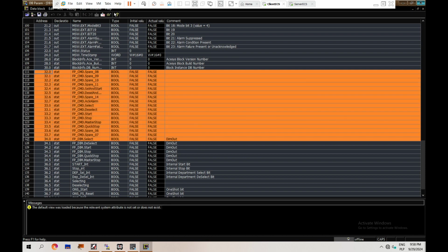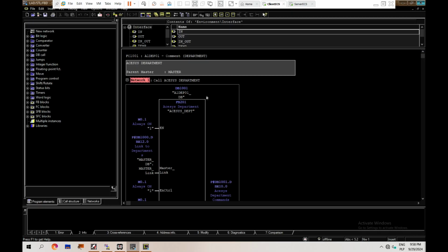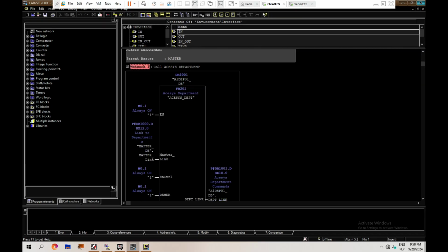We set the type to 16 bits in the configuration because we only want to read exactly 16 bits of data. Finally, the parameter field refers to parameters that we can provide to our department from the ECS system, such as timings or other configuration parameters. In our case, it will always be the data block number linked to the function block call for the given element. In a similar manner, other points such as groups, unimotors, alarms, and analogs are added.